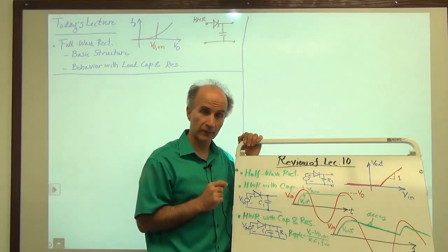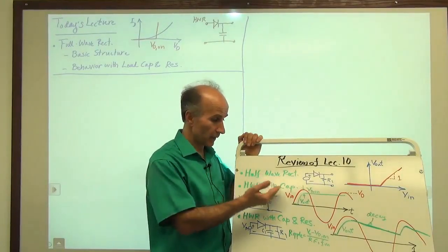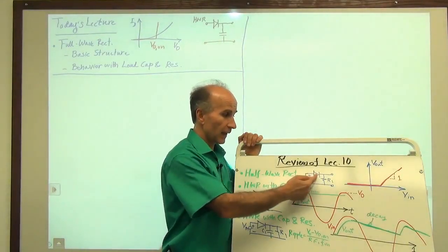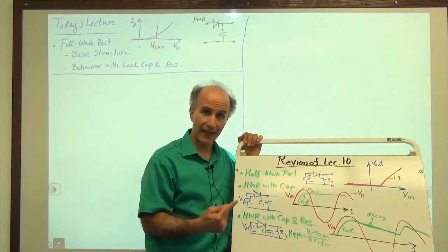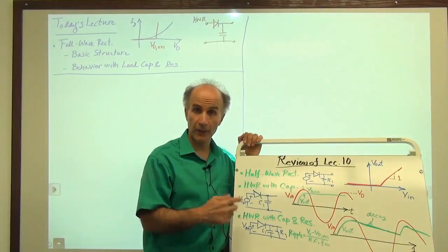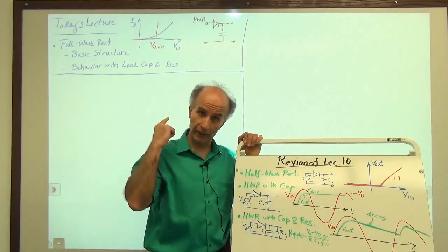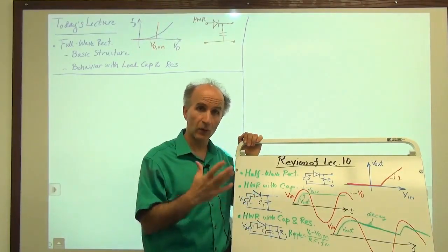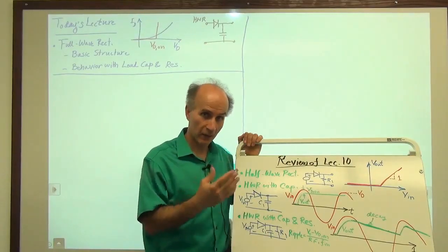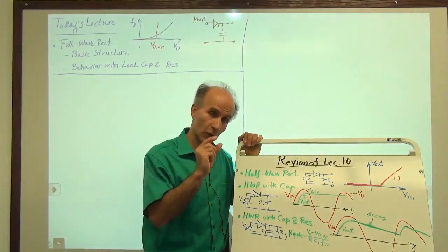half-wave rectifier. So if in this design I decide that this diode must withstand a reverse voltage of, for example, 20 volts, then when you go to the full wave rectifier, we need to withstand only 10 volts. So that's also an improvement in terms of the choice of the diode.